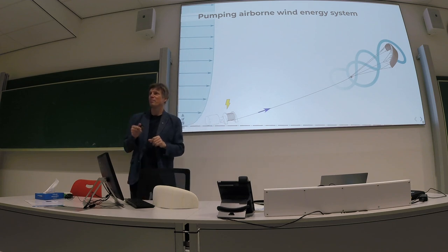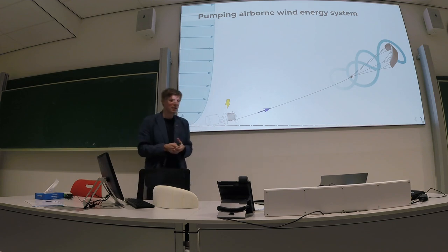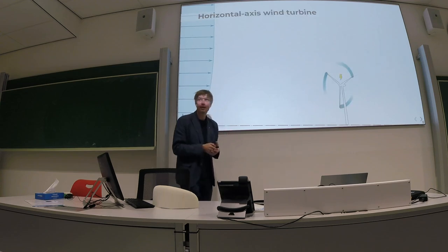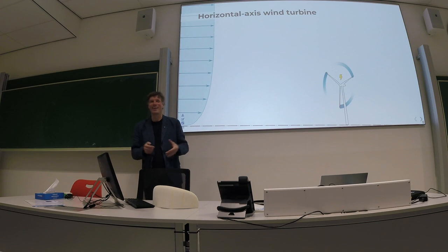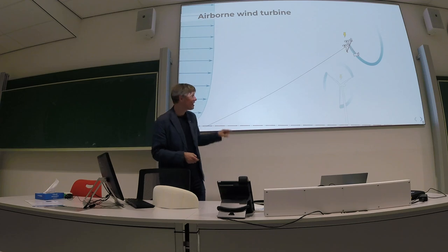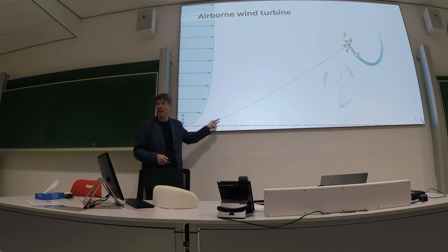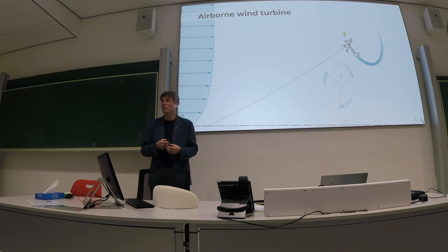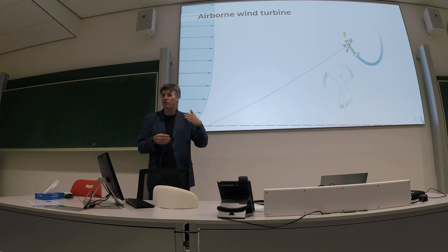Yeah, what happens when there's no wind? When there is no wind, this will just stop turning. This can continue flying if you reverse the energy and pump into the kite, because then you can use the turbines as propellers and fly. You can do this for a time when there is only a small dip in the wind. Then it's actually quite useful to avoid a landing, because landing and relaunching is always tricky and more dangerous.